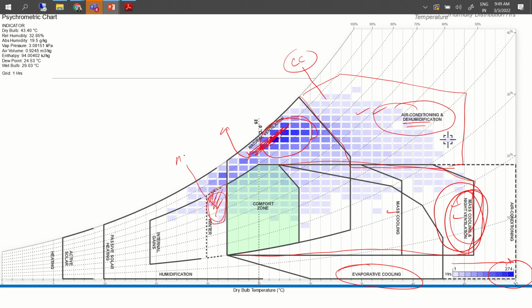We can count the number of hours, okay, which is considered as winter as per this model. Okay, do we need passive solar heating? There's no need, because none of the temperature or data set falls in this area. Okay, so there's no heating required, there is no active solar strategy required, there is no passive heating required. Okay, internal gains, there are certain slight issues. Okay, but I think these can all be well managed in the design itself.